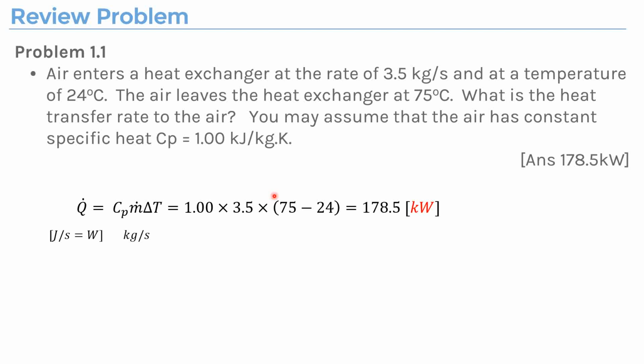But if you have done enough practice, you will see it doesn't matter, and it doesn't mean it's a wrong value that you have to convert Kelvin or Celsius. Because this is basically saying, for a kilogram of material to increase the temperature by 1 Kelvin or 1 Celsius, how much energy, in kilojoules, it needs. So in this one, the only thing you might neglect is if we give you specific heat in kilojoules, then your Q dot heat transfer rate will be in kilowatts.